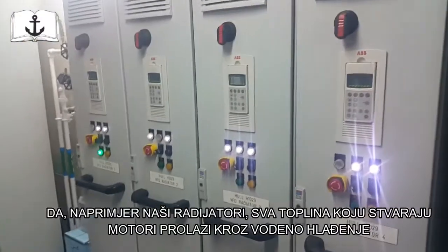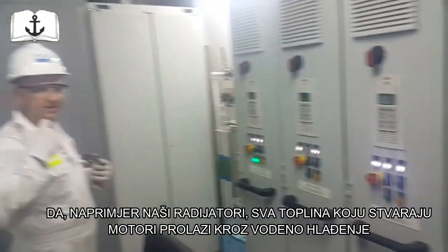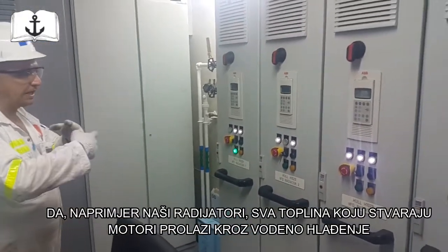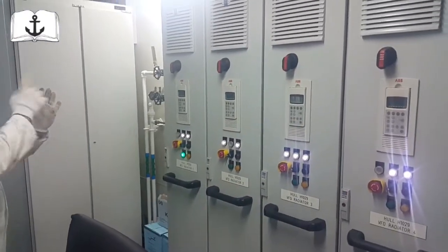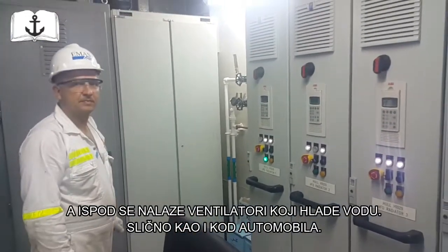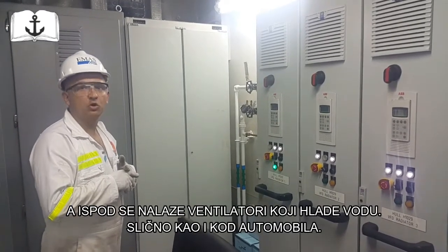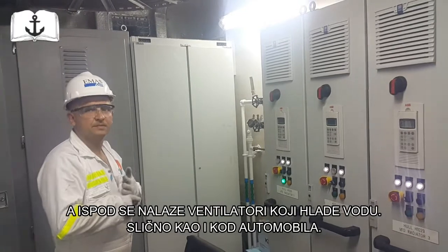We have the radiators here on the deck. So basically all the heat created by the engines is going to the water. The water system is cooling the engine. It's going then to the radiators, and there is a big fan, and the fan is cooling out the heat. So cooling is done the same like in a car, let's say? Yeah, like old cars, you have the fan, radiator, and that's it.